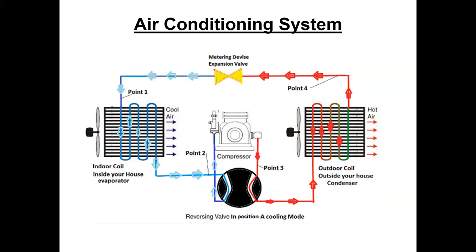And we'll find out that basically it's going to boil it away, like boiling water on the stove, but it's going to boil that refrigerant from a liquid into a vapor. And so that energy is inside that vapor, and it's going to go into that compressor. It's already a vapor. It's low pressure. That compressor heats it up, puts a bunch of energy into it, right? It's hot. How hot's the refrigerant coming out of a compressor?